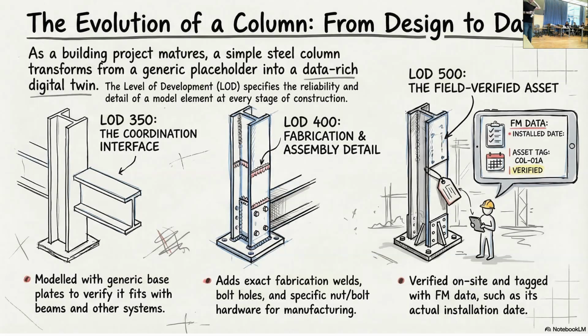And we found out that the bolts were not torqued properly. They were not even tight. So I don't know how they missed it, but they were not even tight. And we found out that only by finding the paint going below the bolts.